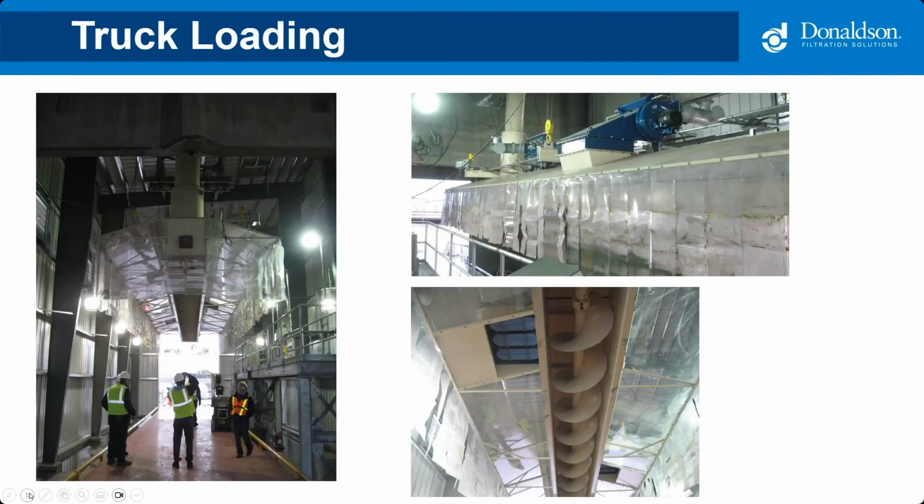Truck loading is very similar to truck unloading. Here, we're just doing it from the top. If you look at the picture in the top right-hand corner, that's a couple of point source dust collectors. When this process is being done and the truck is being loaded, actually we can have the truck finish loading, then we can just wait a few minutes and this will pulse the dust right back into the truck, and it's a way of capturing that value of the dust.